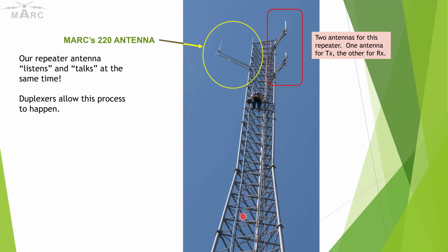The transmitter wattage that's coming up that heliax is only 40 watts or 35 watts. But because the antenna is a high gain antenna, which means it has like a 7.8 dB gain on it, and the height, we are at 180 feet above the ground, the effective radiated power is 340 watts. So it's as if we are on a 340 watt transceiver, and this is why it works so well, okay?